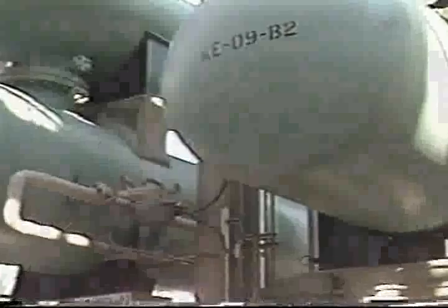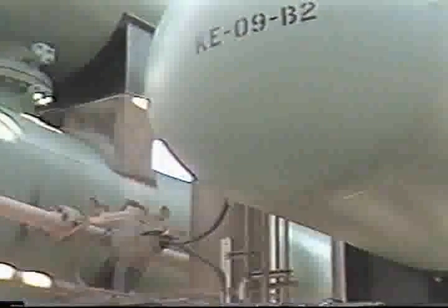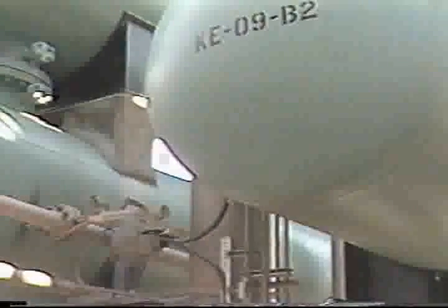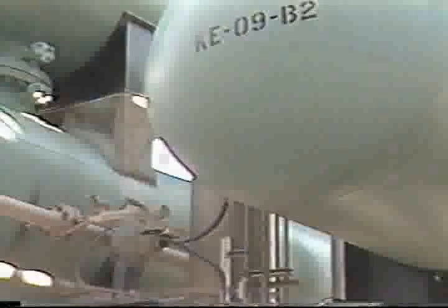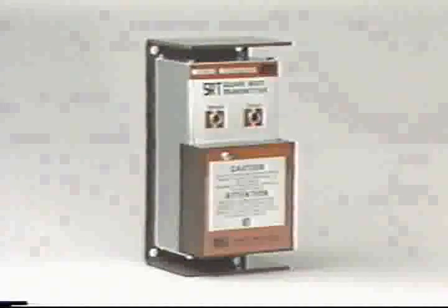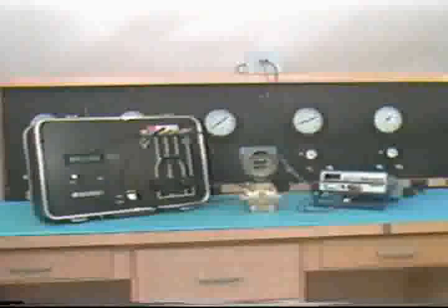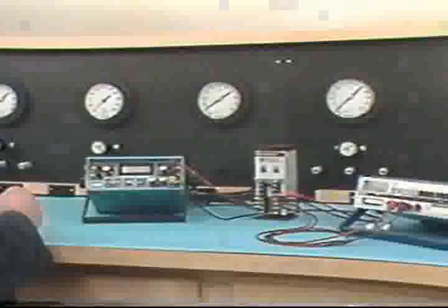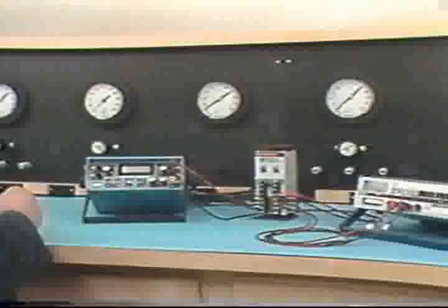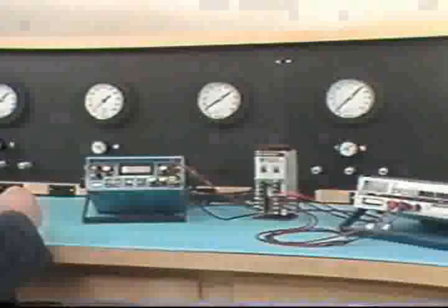In this segment, we've seen one method for measuring flow inferentially using a differential pressure transmitter. Here, accurate flow measurement relies on a properly calibrated transmitter. Sometimes differential pressure flow transmitters require a separate square root extractor located in the output signal line. This instrument, too, must be calibrated to help ensure that flow is measured properly. The input and output standards are chosen to simulate the actual process input and output signals used in the loop. Sometimes, test points may be specified by the manufacturer. Now, stop the tape to review what you've seen in this segment.